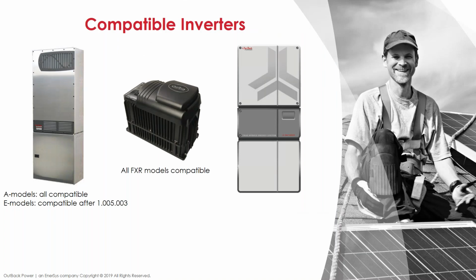And our compatible inverters, so you see here the Radian, either 80 or 48 A models, all of those are compatible. And the export models, they're all compatible as long as you have firmware version greater than the one I have here on the screen. And all of our FXR models are compatible with lithium. Just to be pretty specific, they do need to be FXRs, so not FX or GTFX or any of these things. So the newer FXR models are all compatible. And of course, we have here on the right our Skybox inverter, and there's only one version of that, so of course that one's compatible.